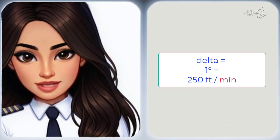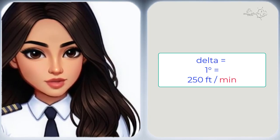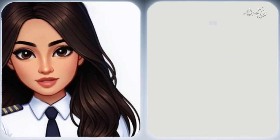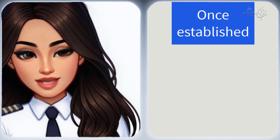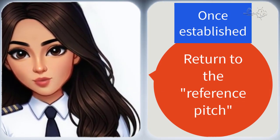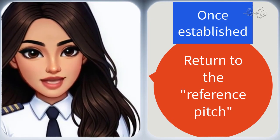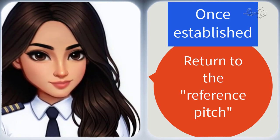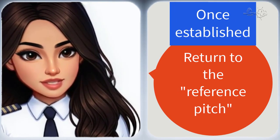Thus, the correction on pitch will result in a smooth and controlled interception towards the approach profile. Once the aircraft is back on profile, pitch up 1 degree towards the original reference pitch, and you will find the required vertical speed of 750 feet per minute to continue the 3-degree descent profile.